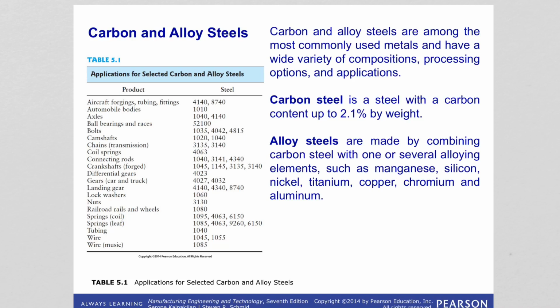So we know steel is an alloy that consists primarily of iron with a carbon content between 0.2 and 2.1% by weight. And that's what we call steel. And alloys that have higher carbon weight, that is more than 2.1, we call those cast iron. So when we say steel, it will have a carbon content between 0.2 and 2.1% by weight.